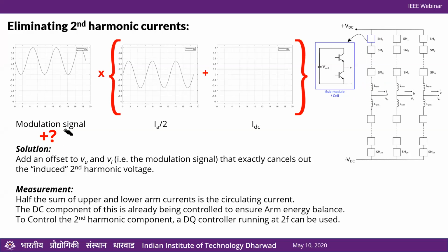One more other thing to note is that we want to do it in closed loop sense. We cannot do it in open loop because, as you know, the value of that current depends on the exact values of this capacitance, right? Because the ripple depends on capacitor value. We don't know exact values, capacitors age with time. There's so many issues. So we want to do it in closed loop. We want to do measurement and then we want to cancel that out.